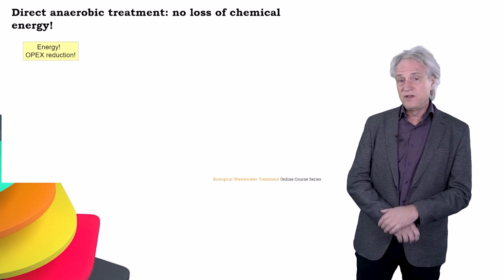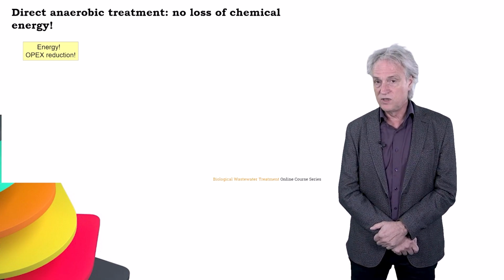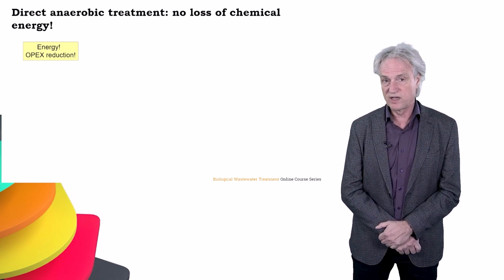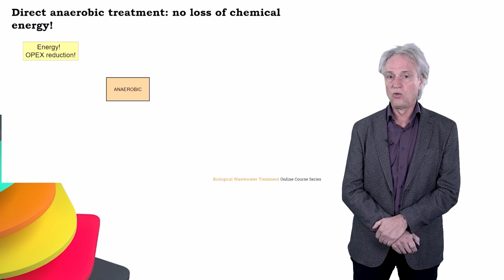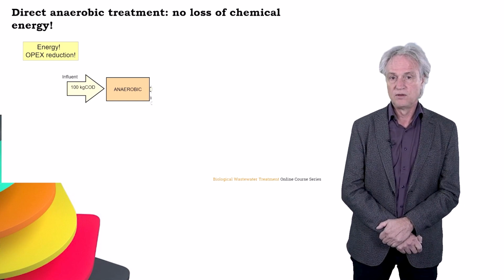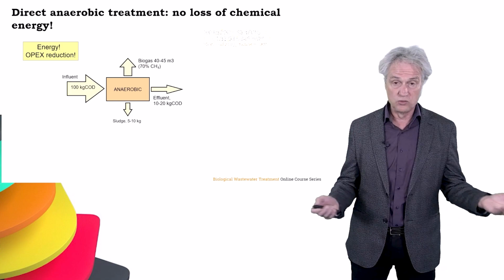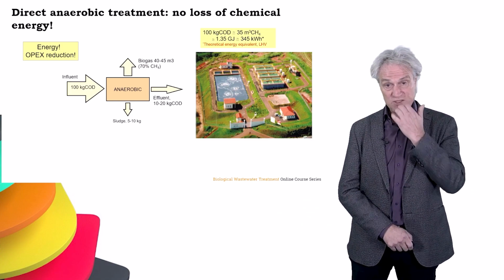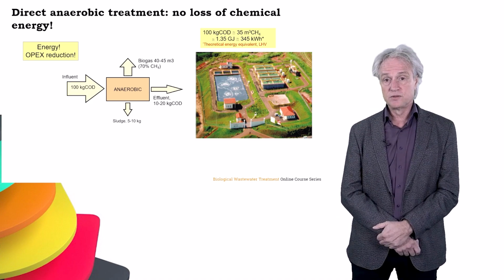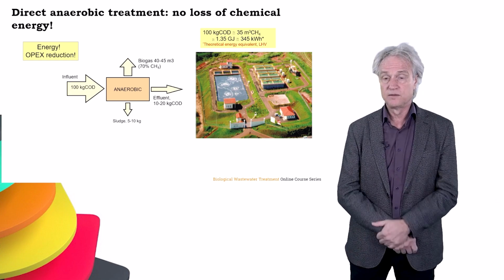Comparing this, if we now directly go for anaerobic treatment, apparently we do not lose any biochemical energy content of the organic compounds. In fact, all the energy is retained. We enter an anaerobic reactor with 100 kilograms COD. We do not need aeration energy. We see that as little sludge is being produced.